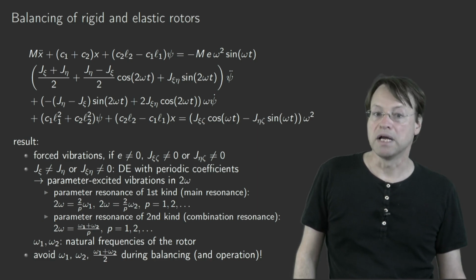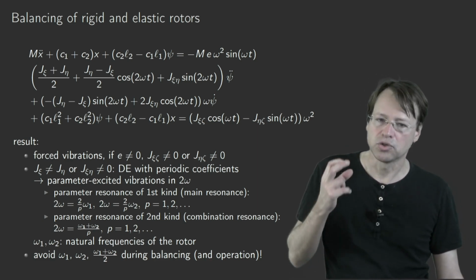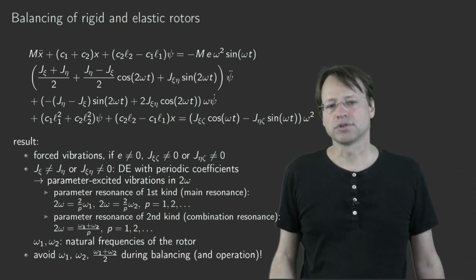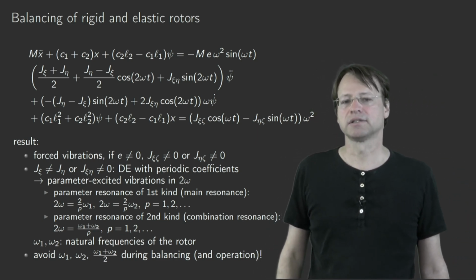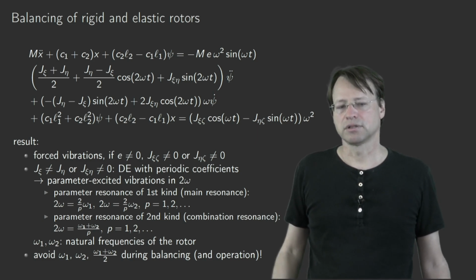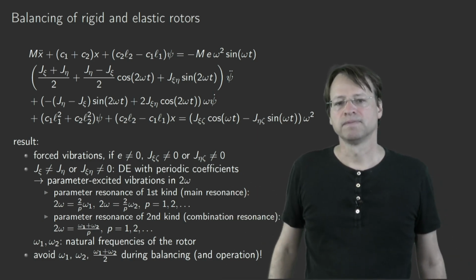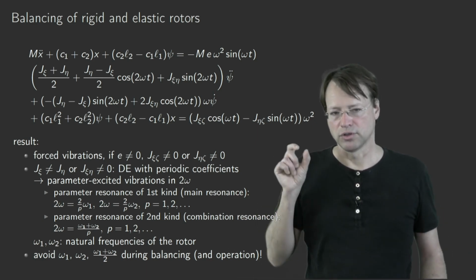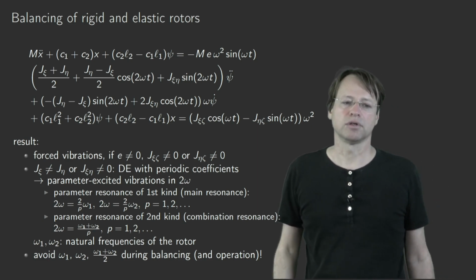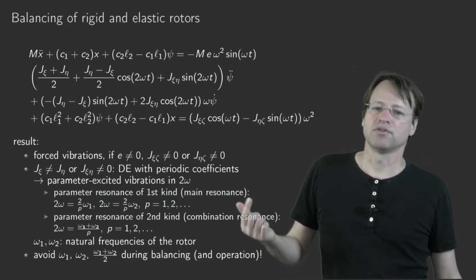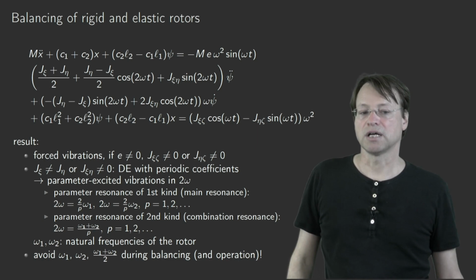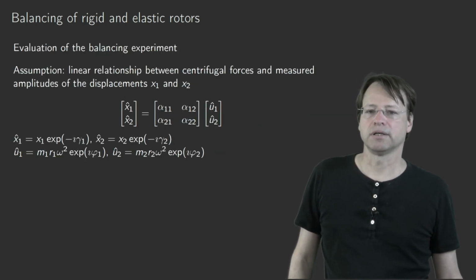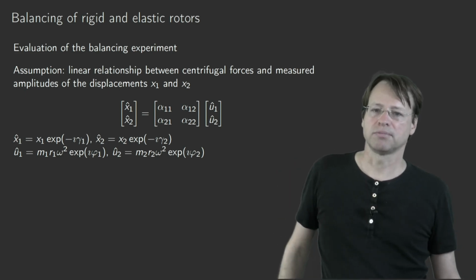How do we balance a rotor? So how do we determine the forces at the bearings, the forces that are needed to counteract these bearing forces, so these forces that we need in the balancing plane in order to add there some mass points and in order to balance the bearing forces by the centrifugal forces of these mass points. So the first example I would like to consider is, well, I would start first with some assumptions.